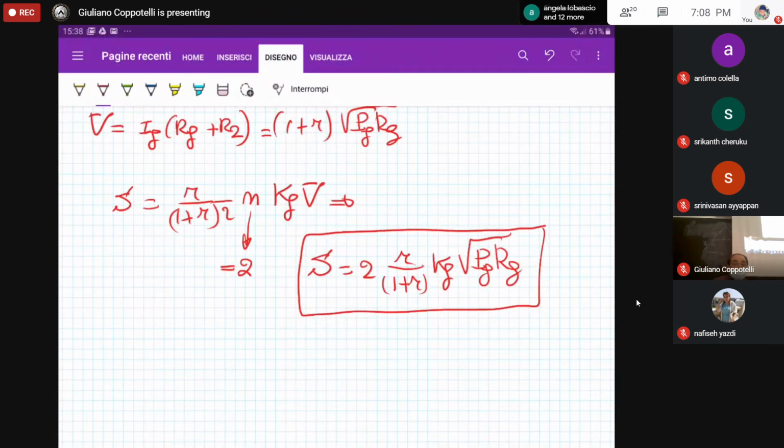If you place a dummy strain gauge on leg number 4, that is a strain gauge operating close to the strain gauge on leg number 1, feeding the same temperature field without touching the structure, then you can say that there is temperature compensation. Can you consider that accurate, even though it's a dummy strain gauge? Yes, why not? It's up to you.